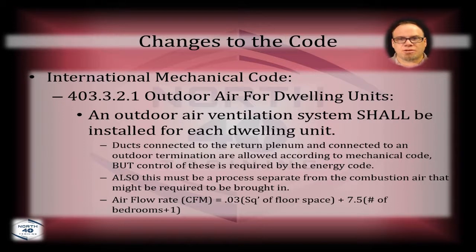Not to mention, you can't be within 10 feet with your fresh air intake from any exhaust. So think about that. You've got this little corner room where you've got a furnace and a water heater set up, and potentially you could have to go out one side with the water heater because it's power vent, the other side with the furnace because it's PVC vent 90%, and then you have to bring in potentially combustion air for that as well.